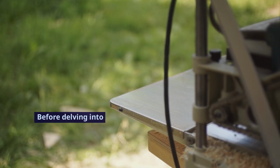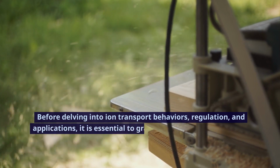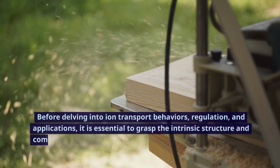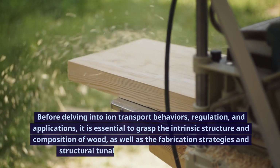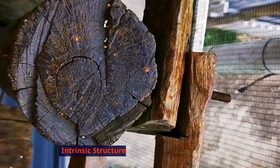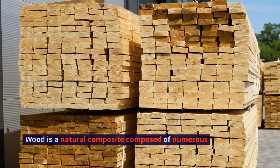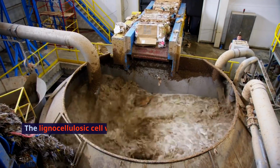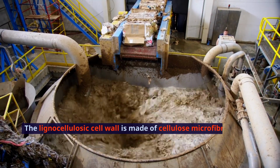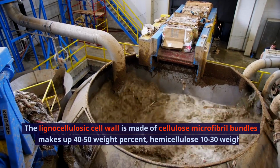Before delving into ion transport behaviors, regulation, and applications, it is essential to grasp the intrinsic structure and composition of wood, as well as the fabrication strategies and structural tunability of wood-based structures. Chapter 2.1. Intrinsic structure and compositions of wood. Wood is a natural composite composed of numerous cells oriented along the longitudinal direction. The lignocellulosic cell wall is made of cellulose microfibril bundles, which make up 40-50 weight %, hemicellulose 10-30 weight %, and lignin 20-30 weight %.